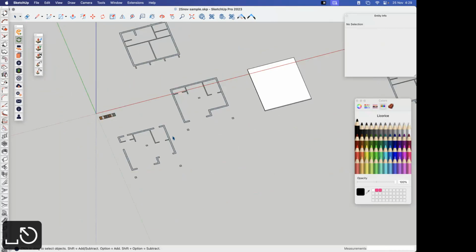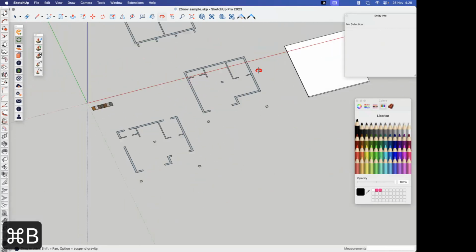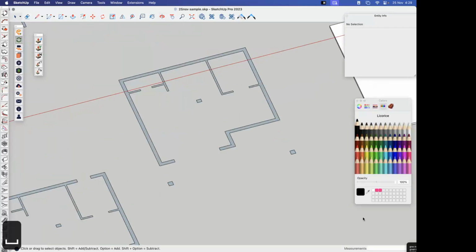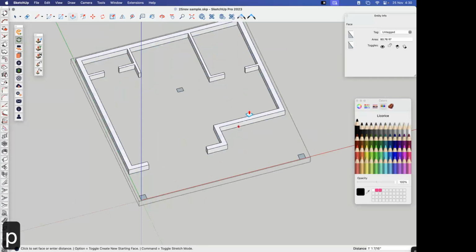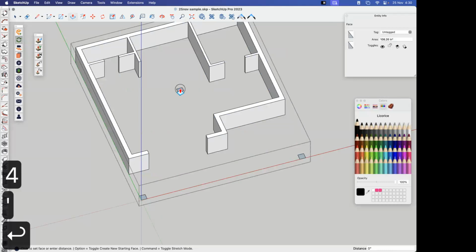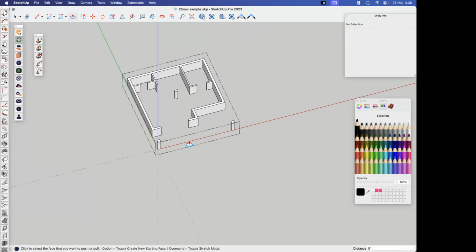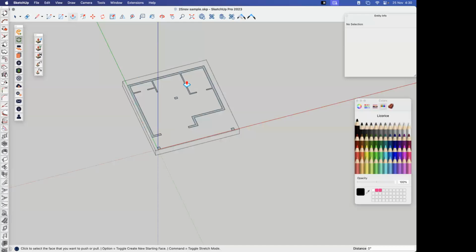So now what we do is we have to pull them to a particular height. So now let's start again with the base. In the base layer, if you were to pull this, so we have sill up till the 4 feet height. So I can just take 4 feet and then pull it off, do individually like this. So now what happens is here I had only 3 surfaces to pull, so it did not take me much time. But let's say you have at least 40, 50 walls at once, then it becomes really difficult to pull all the walls at once.